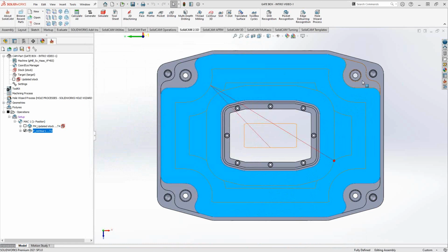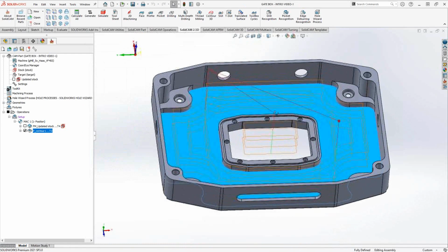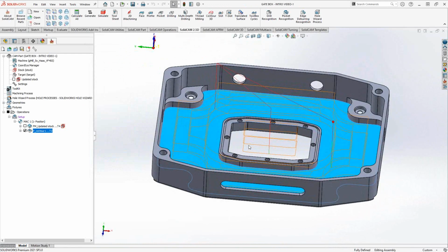So even though we're starting way above this tab, we're only defining it as a 2.5D toolpath. So we can only control it as per the whole target, but with that one chain. So what that actually means is we're going to go around that tab in this toolpath. We're going around that island, and then the only thing we could do in the middle there is just work inside of that island. But you can see that it's trimming all the way around there. That will leave a donut shape around here. There's material there that's represented by that island. So I probably don't want to do it exactly like that.